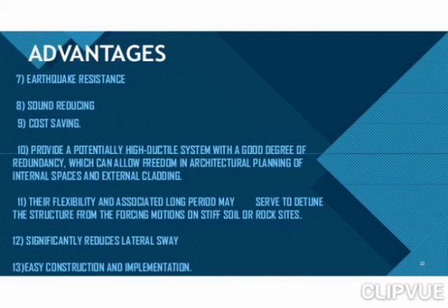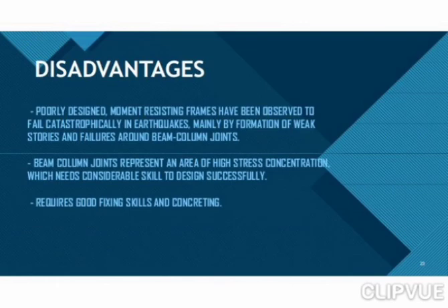It provides a potentially highly ductile system with a good degree of redundancy, which allows freedom in architectural planning of internal spaces and external cladding. Their flexibility and associated long period may serve to detune the structure from the forcing motions on stiff soil or rock sites, significantly reduces lateral sway, and the construction is implemented very easily.